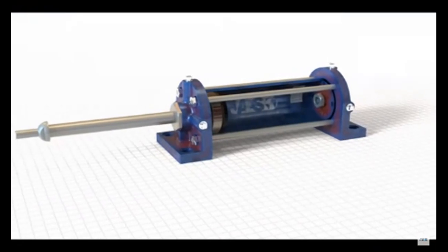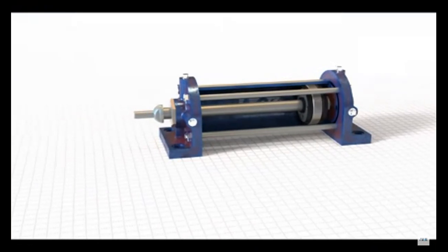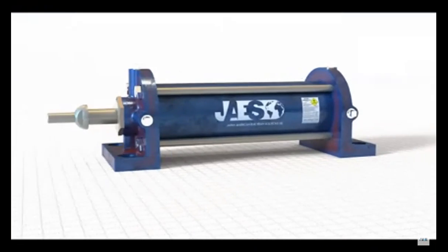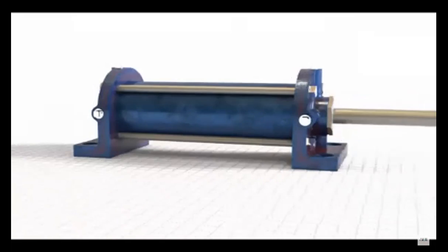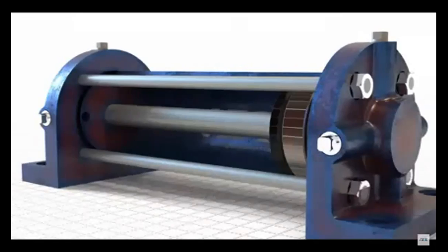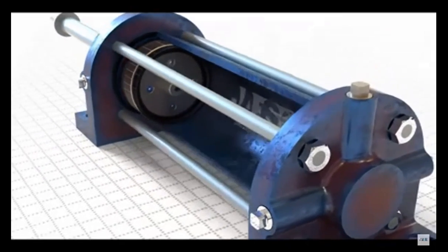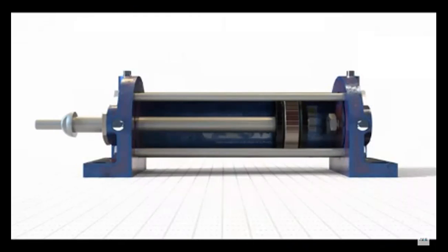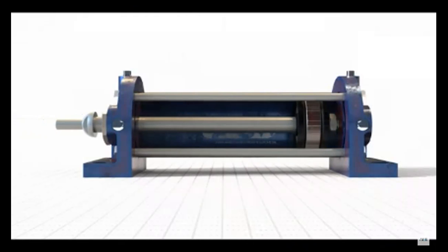Differently from the hydraulic cylinder, the pneumatic one uses a compressed gas instead of liquid. Pneumatic cylinders and actuators are an easy way to gain strength and generate accurate linear and/or rotary movement, and they can be used in harsh environments, even in extreme temperatures. Light and requiring little maintenance, they generally produce less force and a lower speed than hydraulic or electrical systems, but they remain an economically advantageous alternative.